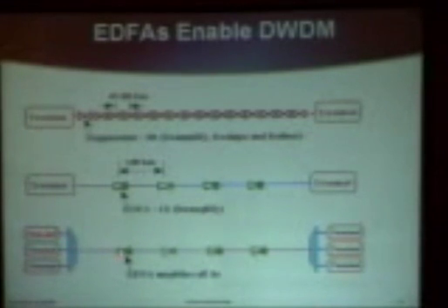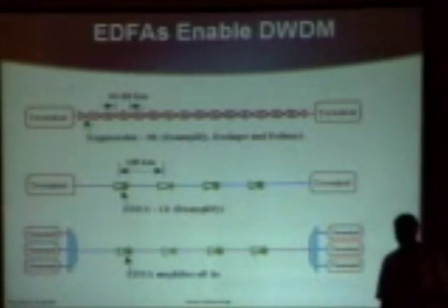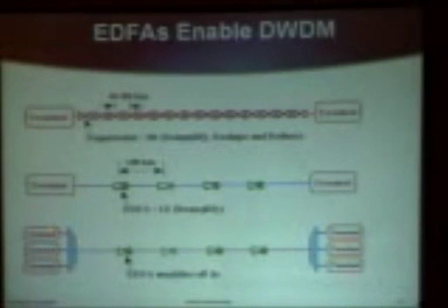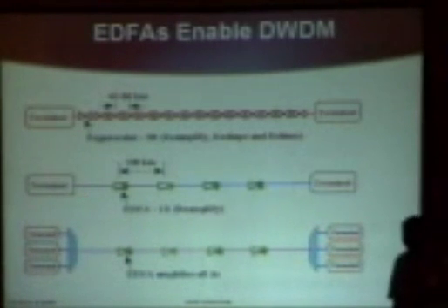The idea was we've already stripped out a lot of the regens, and we put in optical amplifiers. Optical amplifiers can amplify all sorts of signals simultaneously. Let's just multiplex at the optical level many different terminals, each on their own wavelengths, into a pipe and send them down the wire, and the optical amplifier will amplify all of them, and we'll sort them out at the far end.